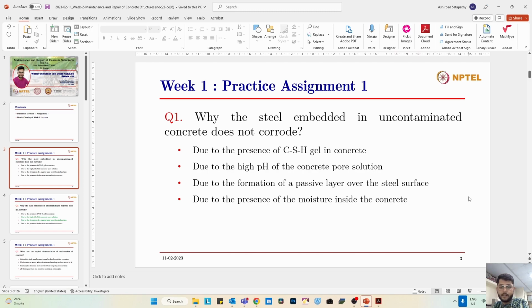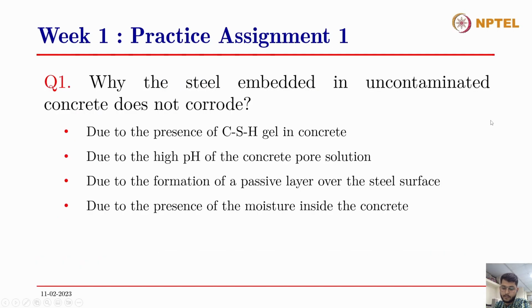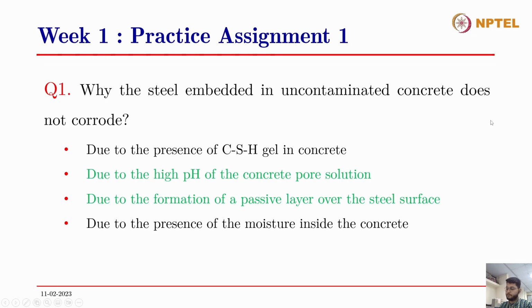Thank you, Dr. Satish. You have rightly pointed it out. So the answer to this question is due to the presence of high pH in the concrete pore solution and due to the formation of a passive layer over the steel surface.